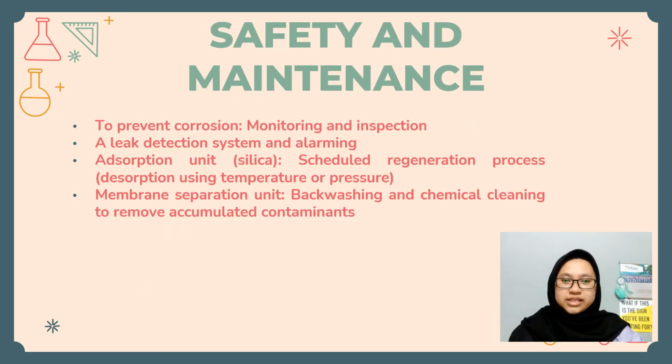As the maintenance and safety precautions, there are a few important points to be kept in control. First, corrosion monitoring and inspection must be done regularly to ensure no corrosion that can block the separation process. Next, a leak detection and alarming system is needed for alert if there is any unpredicted leakage.